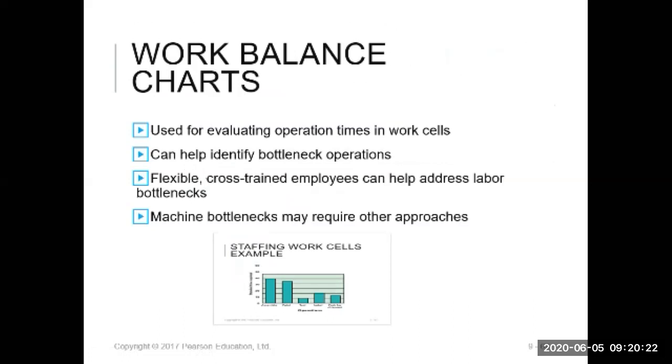If you identify that the bottleneck is because of the employees, maybe you can cross-train employees so that other employees can help the worker causing the bottleneck. A bottleneck happens when the takt time is 48, but this labor completes only after 55 seconds. So they will start later and later, and the products will pile up, so this labor will have a bottleneck. It's easy if the bottleneck is caused by an employee. You just cross-train other employees to help this labor.